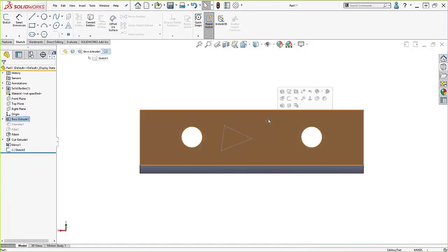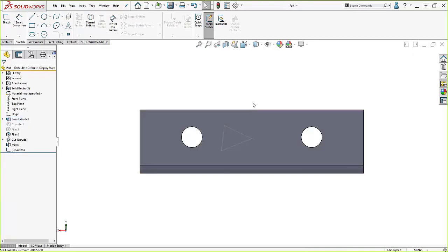Another thing that the D key does is it brings up something else called the breadcrumbs. Now, if you look up in the upper left corner here, these things right here, these are the breadcrumbs, and this is almost a substitute for the whole feature manager tree, because you can see everything from the sketch all the way up to the part in the different feature manager areas. When you're in an assembly, it even shows all of the mates. Okay? The D key brings that right next to your pointer as well. So the D key is very, very powerful.